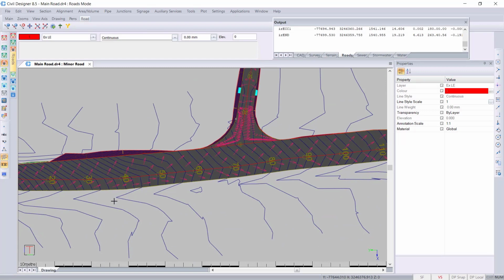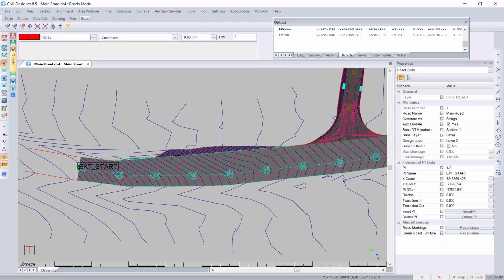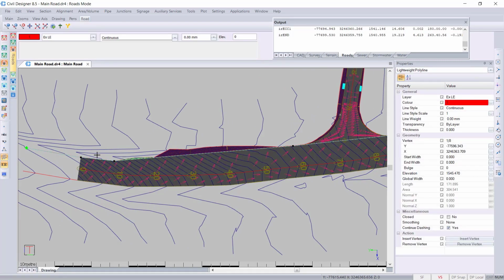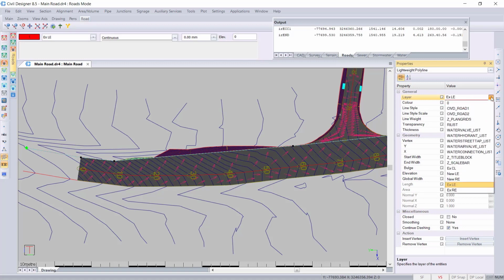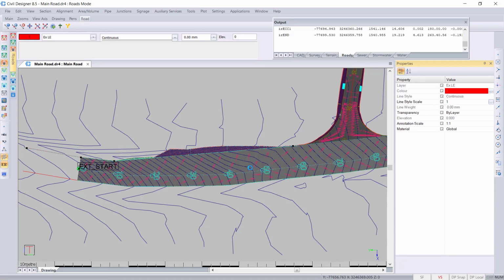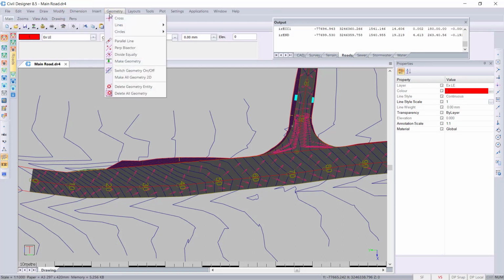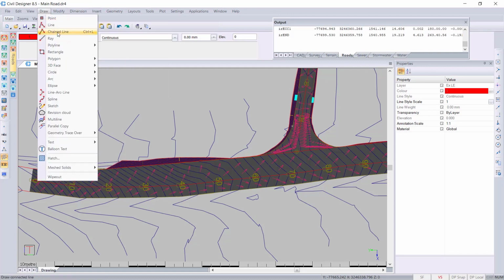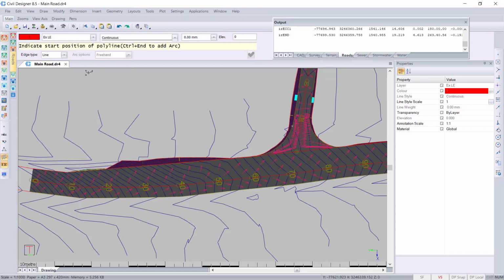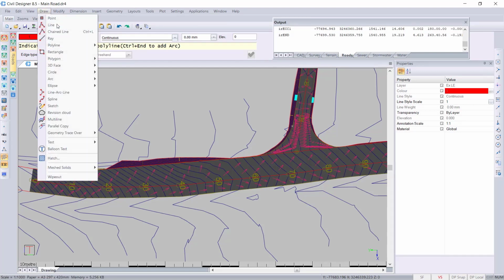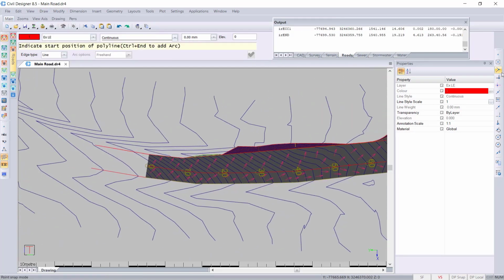Great. We can also quickly just add another edge to this project. Just want to see this edge that we have here, lightweight polyline, needs to be on a layer called new left edge. And I would like to just do the right hand side quickly, and that will lead us into the second chapter. So I'm going to quickly go back to our lightweight polylines, and we will then use the snaps again, snap along this route,